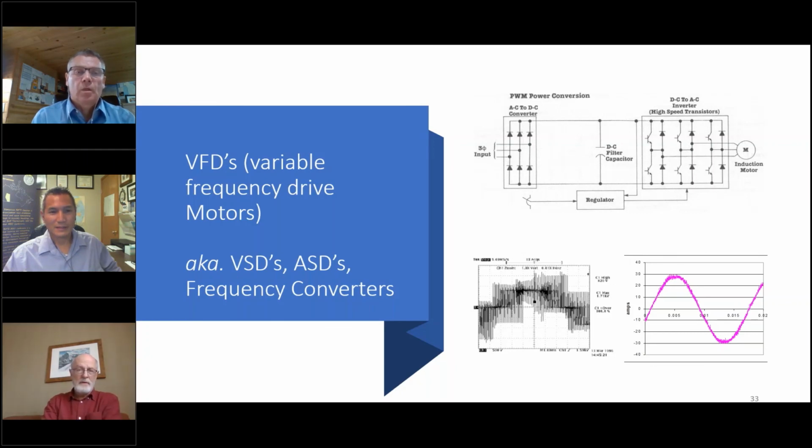Yeah, actually it can. Performance will be a little bit different, but yes, the short answer is yes. If you had a motor data sheet, like a performance sheet that shows you how much torque and current, those values would be different, but there'll be no detrimental effect to running it at a different frequency.